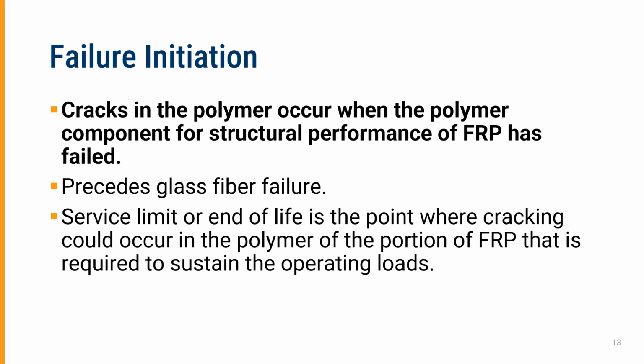If we recall back to the previous slide where we had a fairly thick remainder of that FRP that has the appearance of being undamaged, and I can verify that it is essentially undamaged, that fairly thick zone would be considered the portion that is sustaining the operating loads, and it is probably even more than is required to sustain the operating loads.